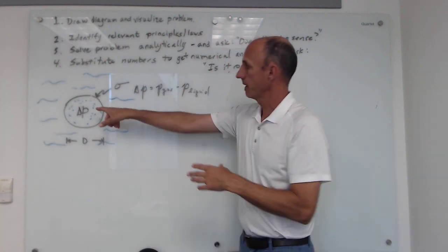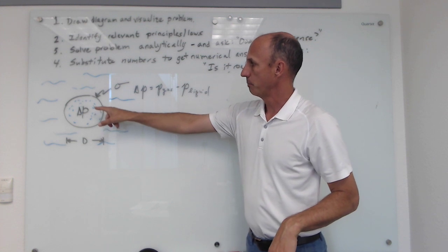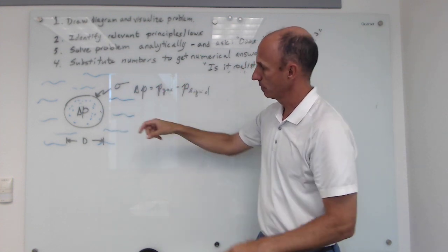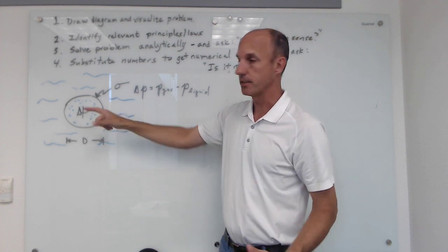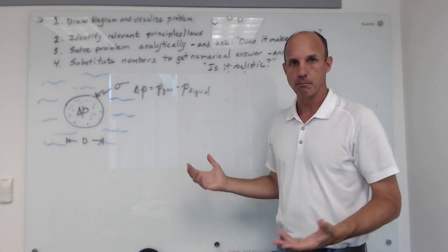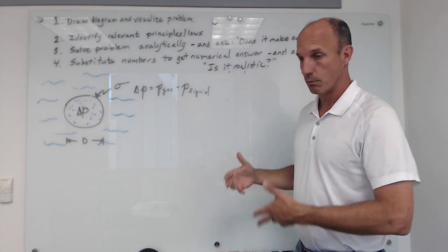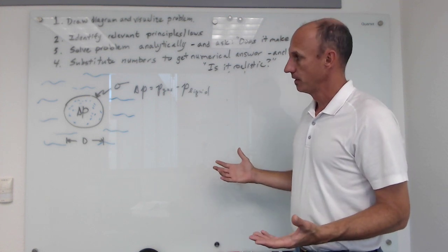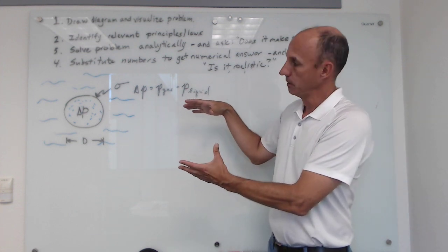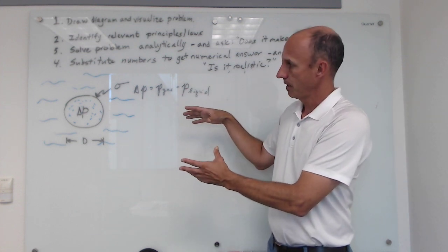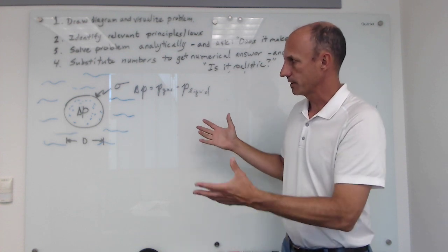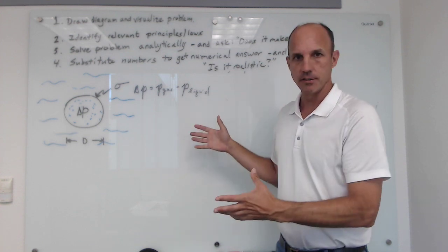We've got this bubble of gas. It's being squeezed by surface tension. Because of that squeezing, we've got a higher pressure inside the bubble. So how do we turn this into a fluid mechanics problem? Well, we bring in the idea of force balances. And because this is a radial problem, actually spherical coordinates, it's tempting to think, oh my gosh, I've got to work this out in spherical coordinates.